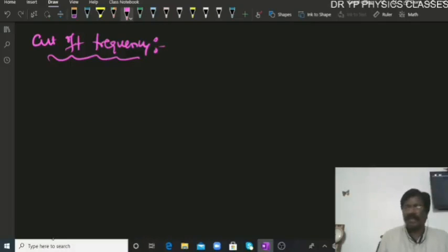So the cutoff frequency of the high pass or low pass filters are the same at some frequency. This is because the capacitor and resistor have the same impedance at this frequency.